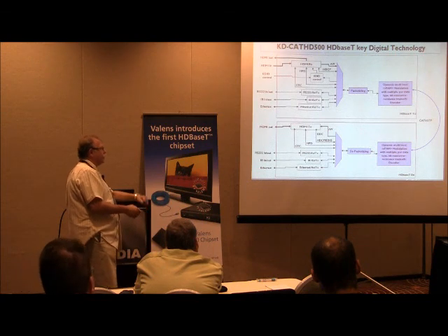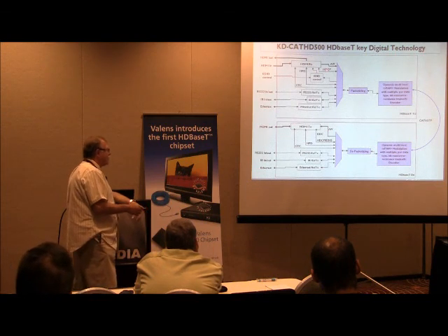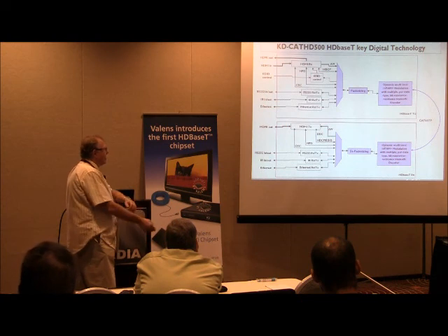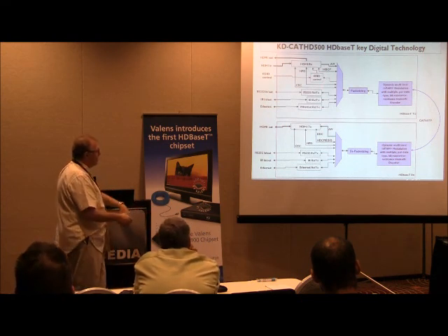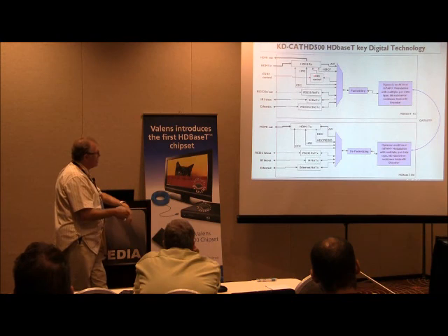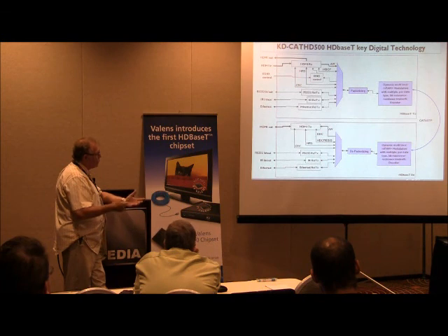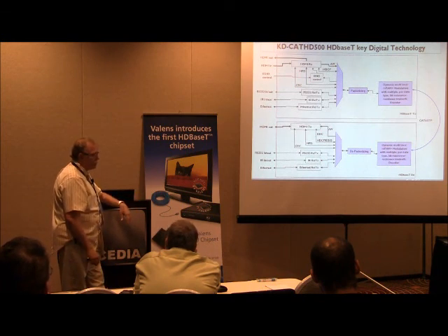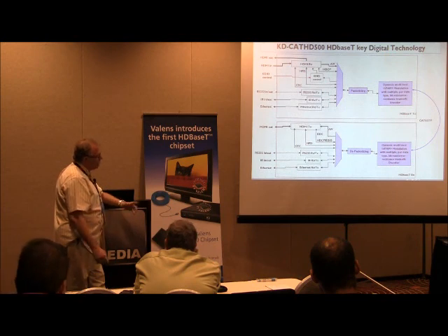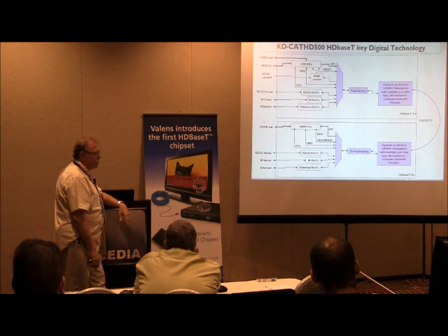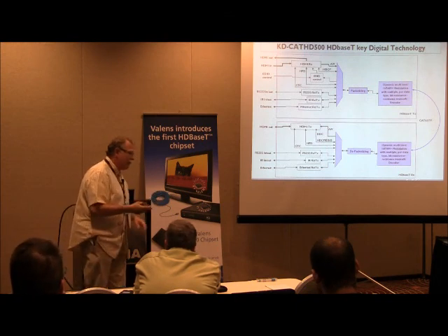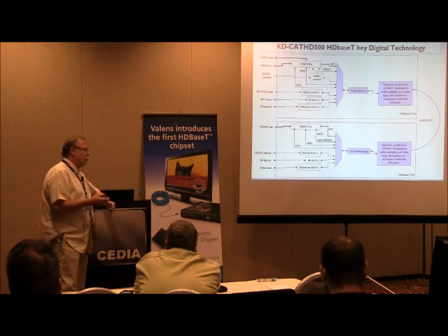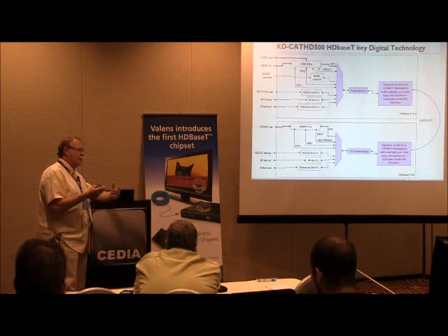So in our case, in addition to it, we also added EDID control. This way we can not only rely on the EDID that comes from the receiver, we can essentially replace it with an EDID from the library that we developed, and it helps a lot in solving many problems in current connectivity, because there are many mistakes that people make writing EDIDs. Sometimes you need a different EDID than the TV provides. The TV sends an EDID for a specific demand, and you may have an installation that requires a different one.